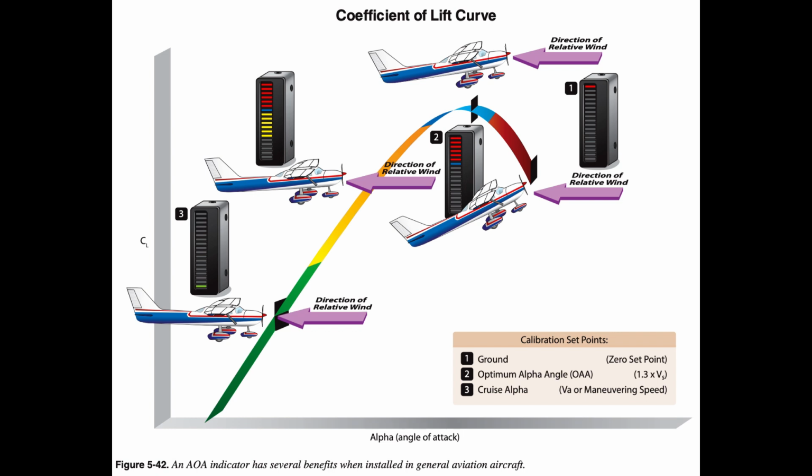These devices can give a visual representation of the energy management state of the airplane. The energy state of an airplane is the balance between airspeed, altitude, drag, and thrust and represents how efficiently the airfoil is operating. The more efficiently the airfoil operates, the larger stall margin that is present. With this increased situational awareness pertaining to the energy condition of the airplane, pilots will have information that they need to aid in preventing an LOC scenario resulting from a stall/spin.